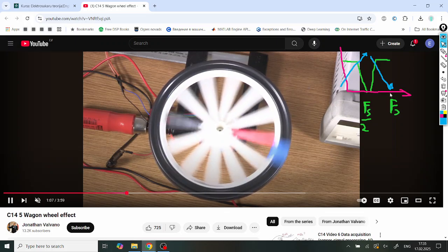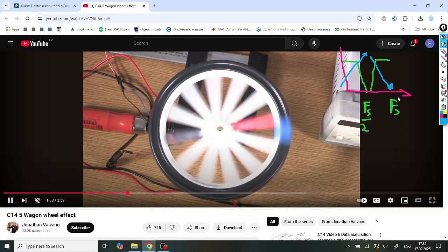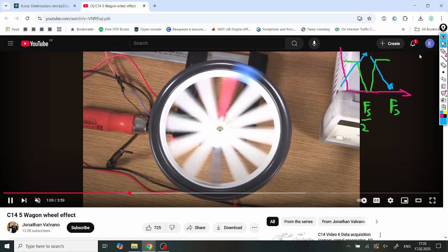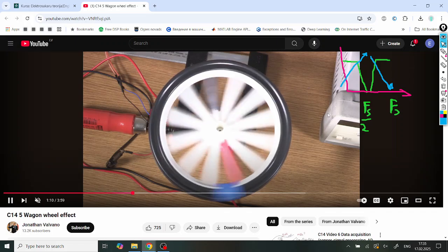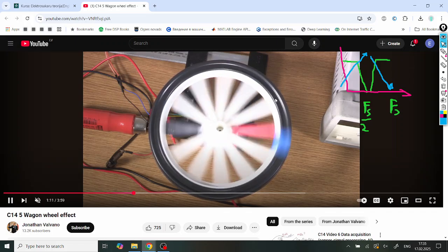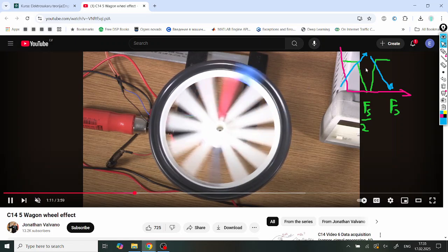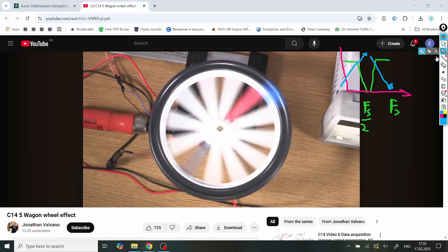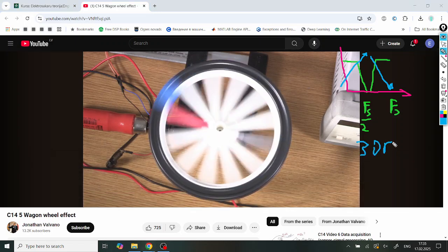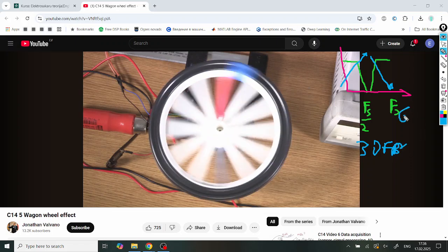And it stops all the way at frequency 0, which is the same as F sampling, and starting from frequency 0, it starts slowly rotating in the other direction. So the process starts to repeat. As the person rotates this knob more and more, it constantly increases speed, but it goes forth and changes direction by passing half of the sampling frequency and full sampling frequency, which in our case is 30 FPS here and 60 FPS here.